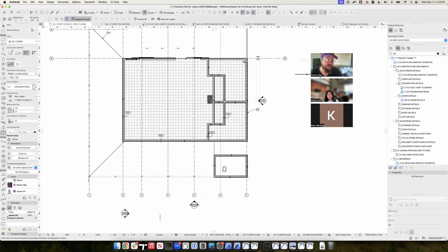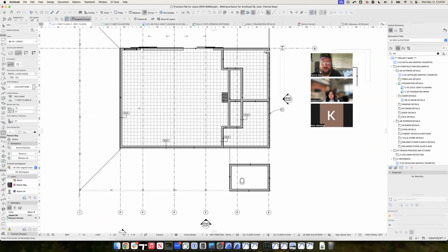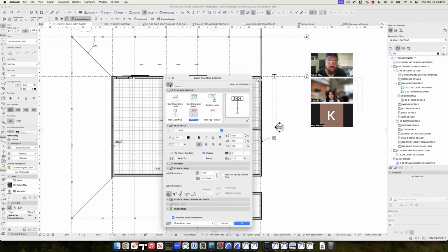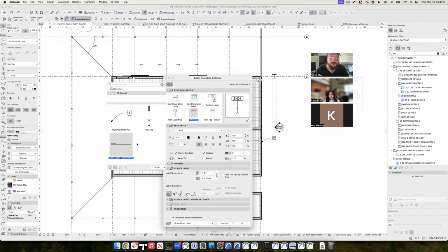Anyway, the construction method on the zone is polygon, rectangular, or associated. Now, obviously, we're not dealing with office plans and stuff. We have a lot of great rooms and open spaces with no zone boundaries. We're not going to try and create zone boundaries where they don't exist. And I prefer to see all using the same method. So, generally speaking, I want to see the rectangular method as a placement. So I can just place a zone here and drop that in. Oh, this should be using the zone label.